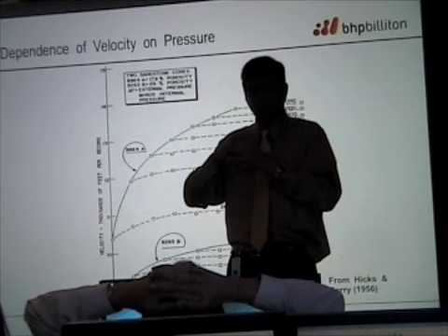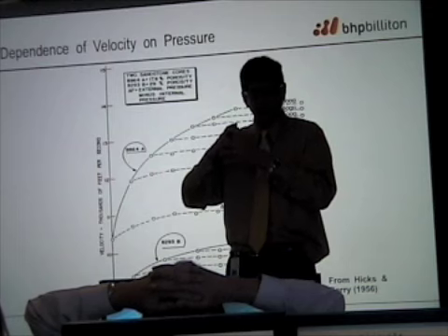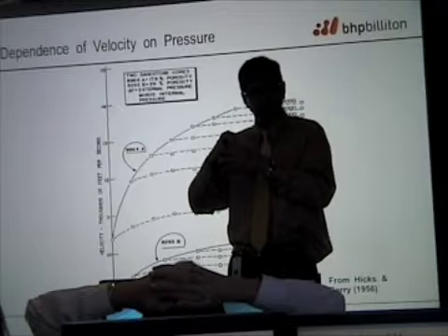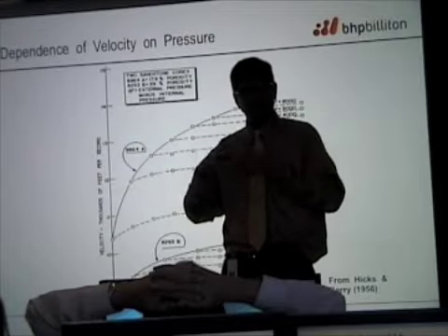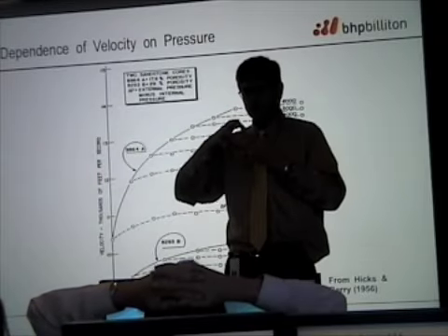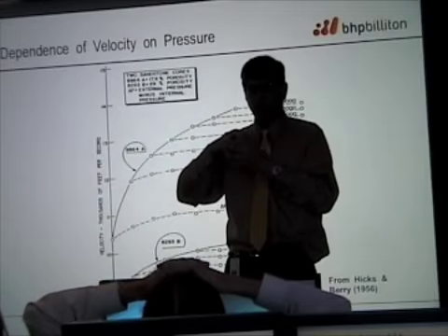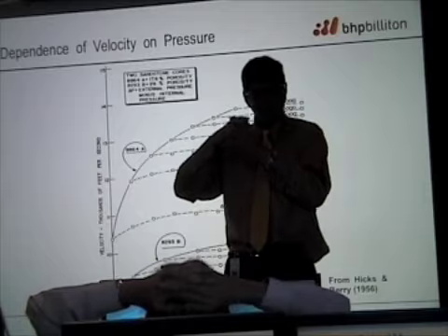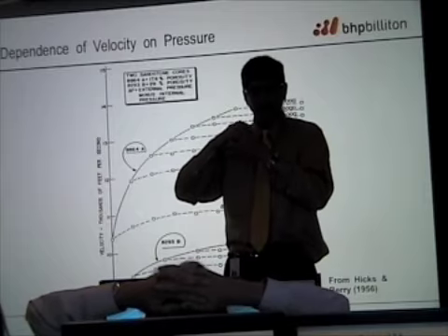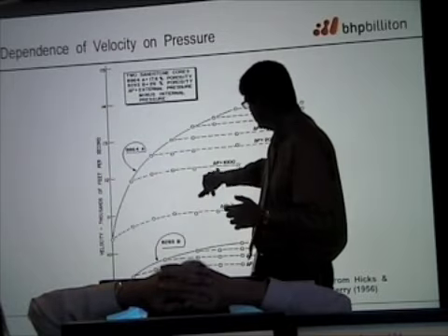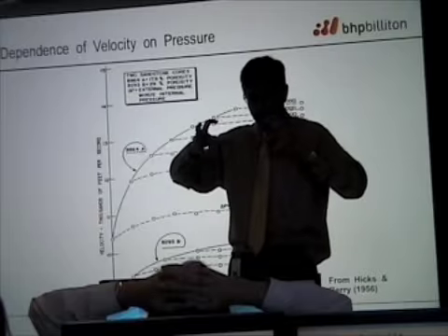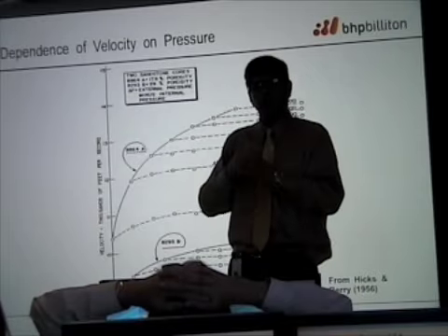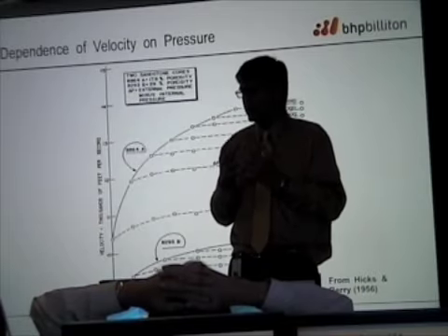And you'll hear us talk about this. The reason why I stopped here is that this is the determining thing in terms of the compaction state. How much have you squeezed that rock? Because the more you squeeze it, the more rigid it ends up becoming. And what matters is the effective stress, or the difference between how hard you're pushing on the matrix, and how much support you're getting from the pore fluid.